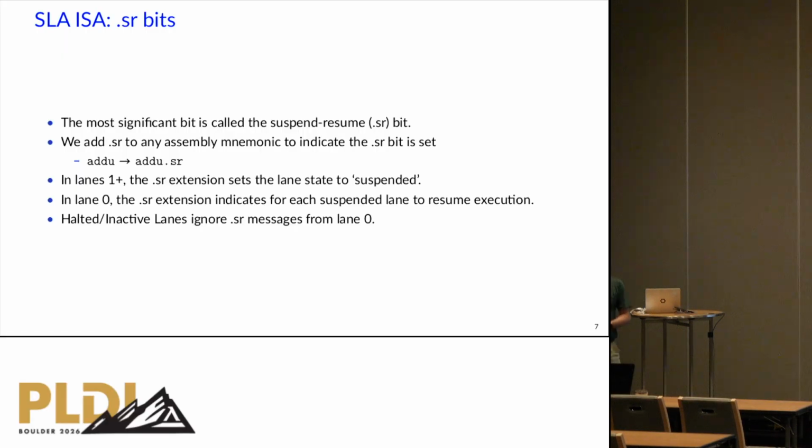And that just says, when you fetch this instruction, don't fetch any more instructions. You're done, and you'll suspend. At least that's true for lanes 1 and so on. So if they see that, that's just the last instruction you're going to run. It'll run through the pipeline and do what it does normally, but it will no longer fetch instructions, and it suppresses any access to the instruction caches, and each lane has its own individual instruction cache.